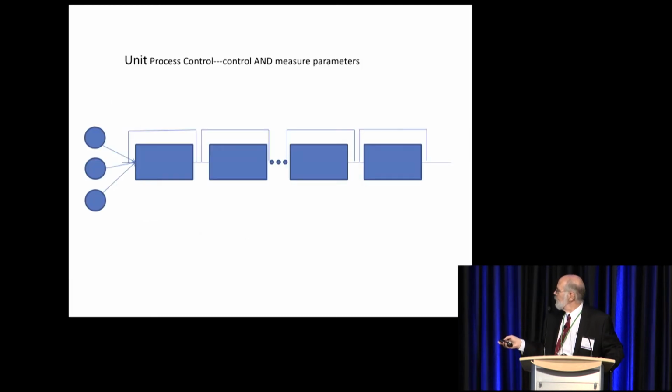Okay. So we instituted a unit process controls methodology. Every one of those steps, which are now a block here, every input, every intermediate, and every output is tracked, and I mean every one. And when any one of those is changed, you know it's noted. So you have a constant record of every parameter through time, and if something goes through this block at a certain date, you know what those parameters are and can later come back and do correlations with it. So the first thing we did is every one of these blocks is under process control, and there's probably 500 of them.